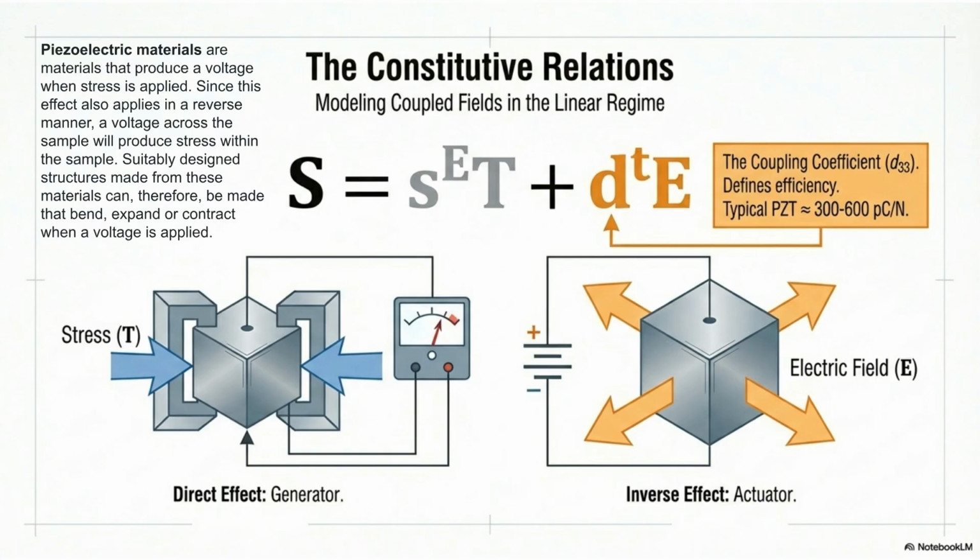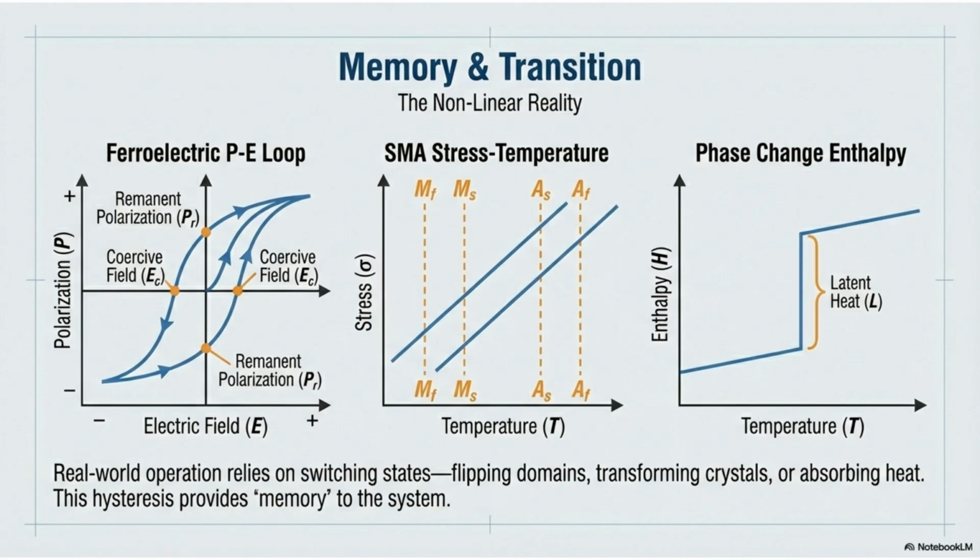Piezoelectric materials generate voltage when stressed, the direct effect, and conversely, applying voltage creates stress and deformation, the inverse effect, or actuator. Real-world smart materials rely on nonlinear effects like hysteresis, which provides a memory to the system. This involves switching states, transforming crystals, or absorbing heat.